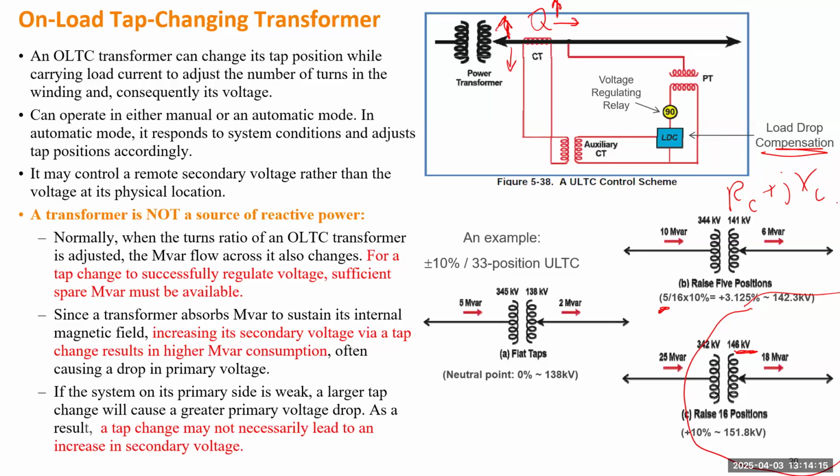Okay. So this one can be easily explained, but I will leave more discussion to the voltage stability session. A quick answer is, if the source is a constant voltage source with some internal reactance, and the load has some impedance which is changing, then when the load is changing, that can cause the voltage to change.